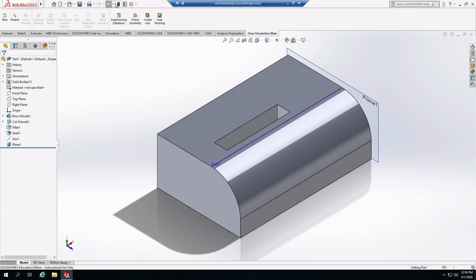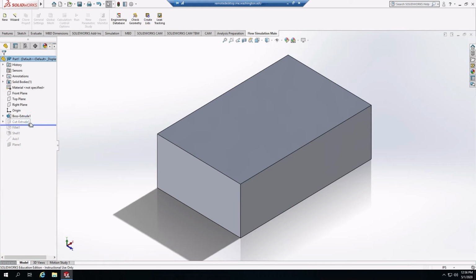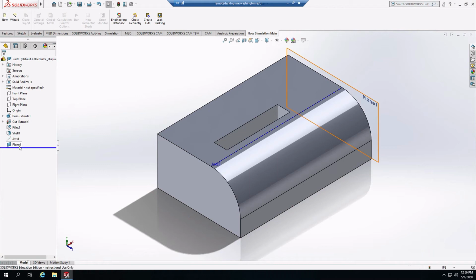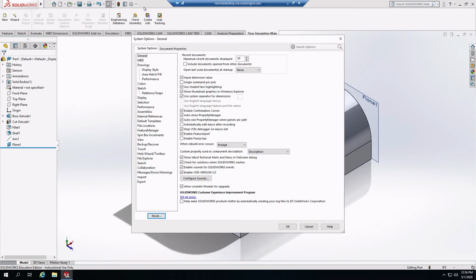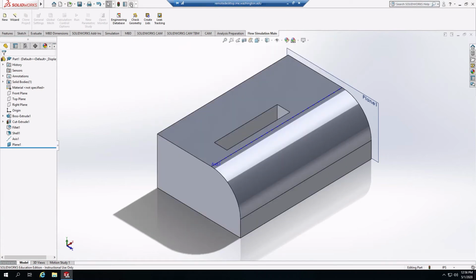That little traffic light up there, kind of like if you make a change and you want to make sure that it carries the change forward and rebuilds, you do that. So make a change in that history over there, hit it just to make sure it carries forward. Hitting that traffic light essentially forces the program to step through the whole history of steps to rebuild the piece you're working on. You can also have additional document settings up there as well that you can go in and edit.